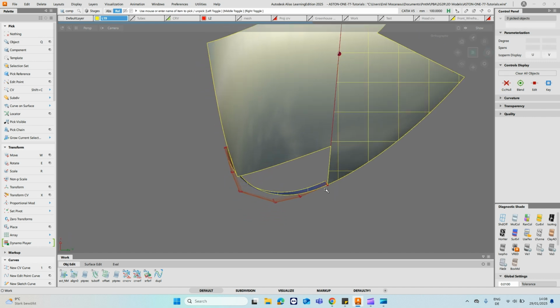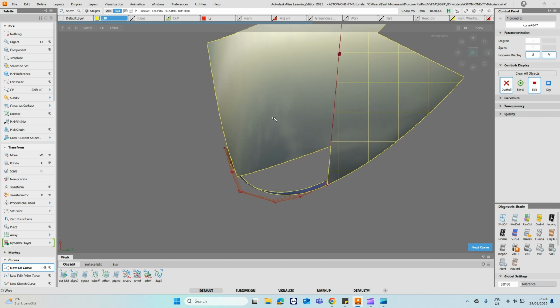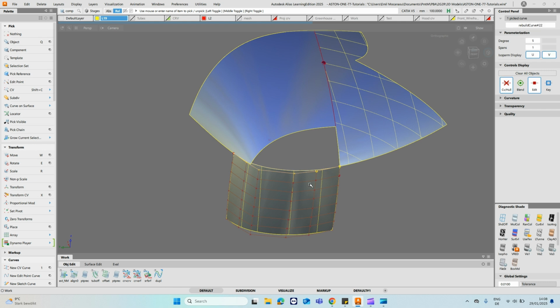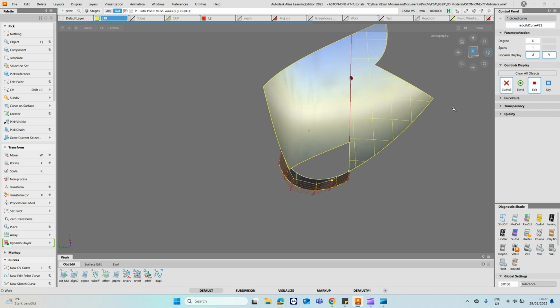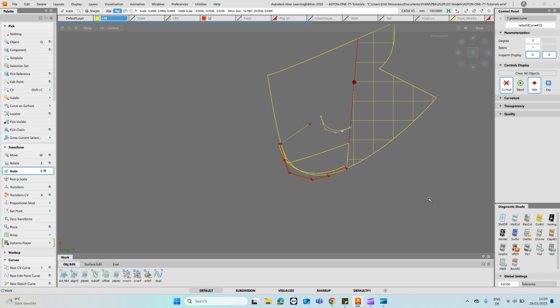And we know the following thing. We've got here one edge on that surface. We've got this other edge, so we'll need two more edges on this surface. So in a very similar manner, we're gonna generate here one curve like this. And now we can duplicate, for example, this curve, move its pivot here, slide it up here, make everything transparent, and then scale it down like that.